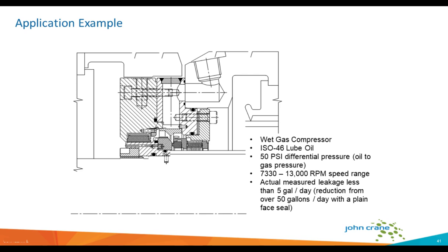So this is an actual application example of Y groove technology for a wet gas compressor using an ISO 46 lube oil, 50 psi of differential pressure, and between 7,000 and 13,000 RPM in terms of the speed range.